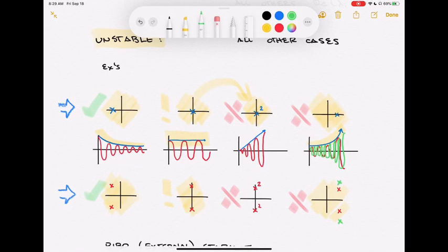What happens when I repeat the root? I get a couple of modes in there. The first one, the lambda equaling 0, the one that's just all by itself, has an e to the 0t, which is just a constant. But what happens when I repeat a root? Then I get a t times e to the 0t in this case, and that is t. And that t term in this particular case is going to cause the overall output to grow without bounds. We see that it grows as a function of t. So when I repeat on the omega axis, that t pattern makes something that was flat before now grow without bound. That's an unstable condition.